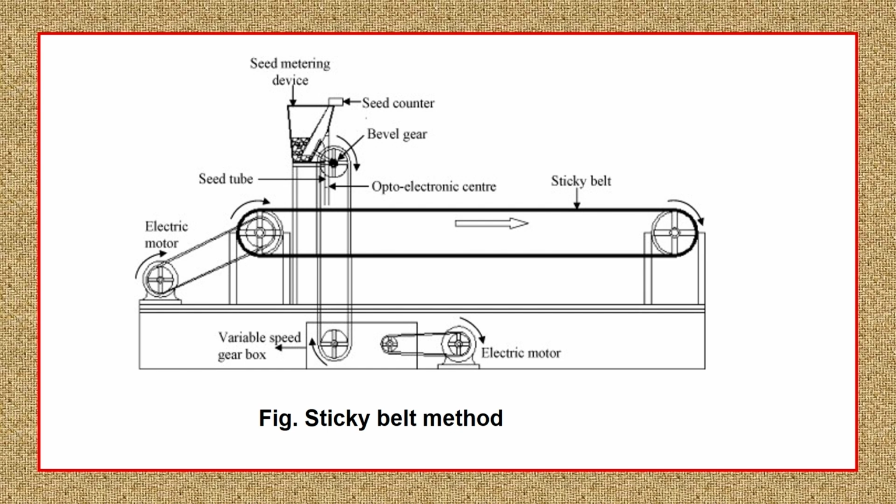Synchronization will be made between the speed of the belt and the speed of the metering unit in order to observe the real working condition as it happens in a field experiment. Like that, with the help of the sticky belt method, the mechanical damage which may happen to the seed at the seed metering unit, at the cutoff mechanism, and at the knockout mechanism will be assessed.